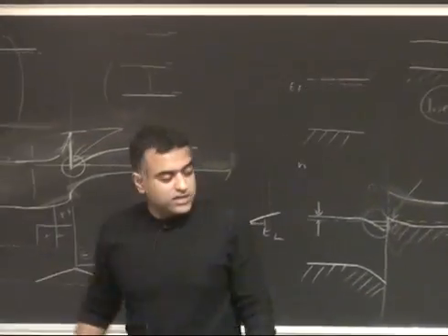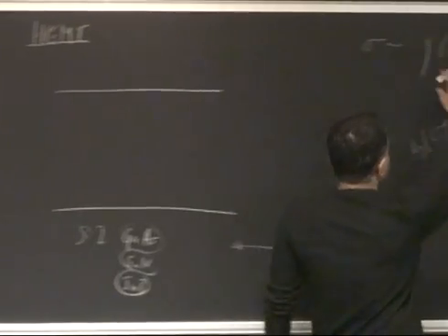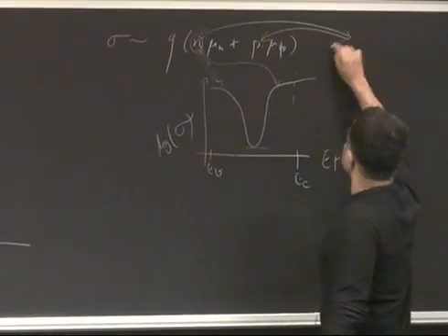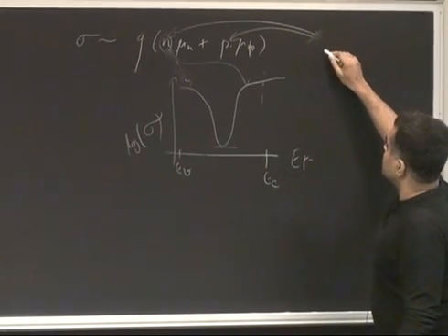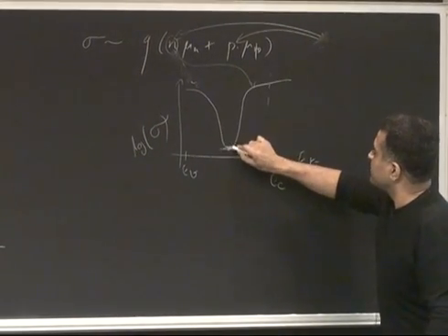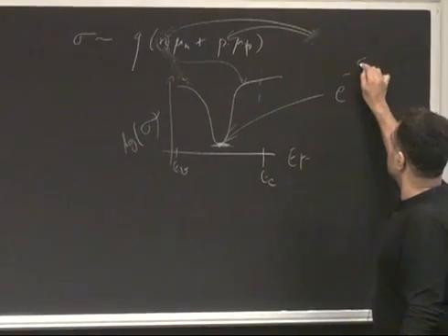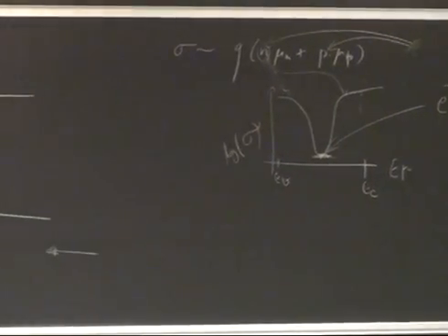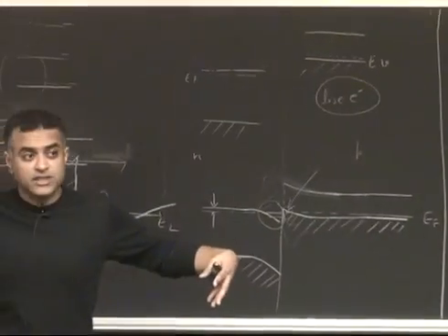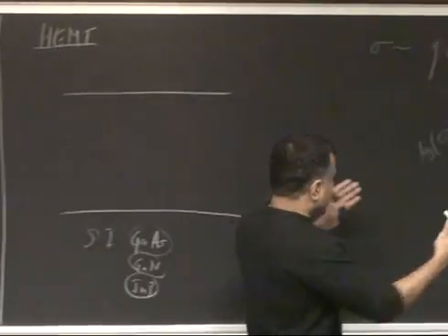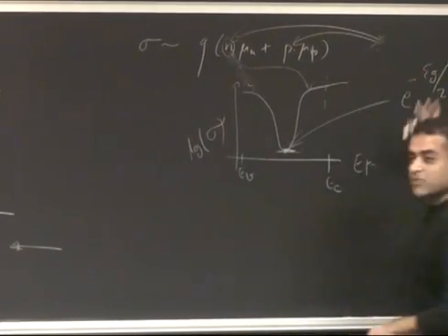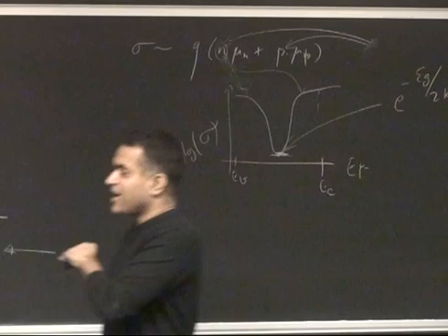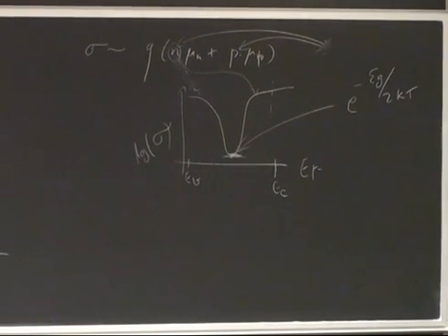The minimum level is something you can calculate, and it will be related. I think you can see from here the minimum carrier density you can get in a semiconductor, which is pure, is related to the band gap. How far away from the band edges have you gone, right? As a result, the wider the band gap of the semiconductor, the more you can change the conductivity. That is a hard and fast rule. You can't change that, at least as far as we know till today.